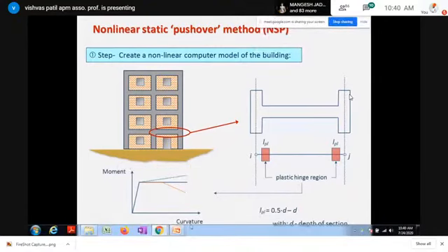First is moment curvature, and afterwards moment rotation. In the case of a column, again there is a rigorous calculation. So we can assign this particular hinge by using an auto hinge procedure, or we can calculate all the properties and then assign the hinge. The only thing is that it is time consuming.